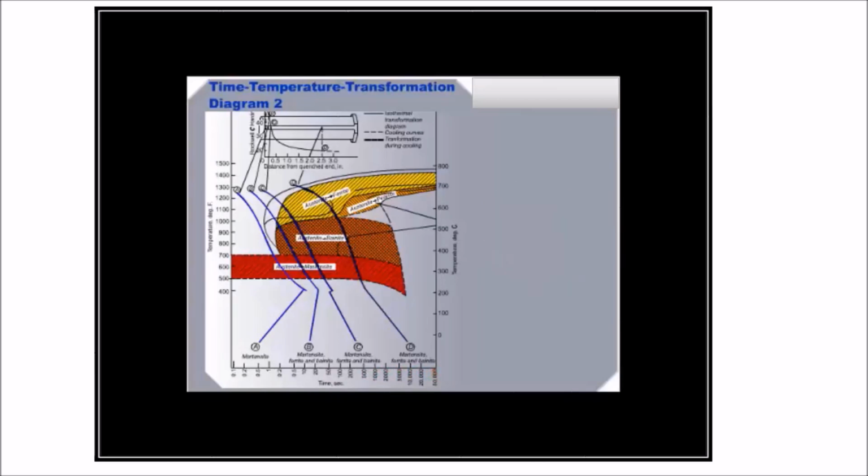As an example, curve A only passes through the austenite to martensite region, so the resulting microstructure is 100% martensite. The slower cooling rate, characterized by curve D, shows that the resulting microstructural components will be primarily ferrite, with only minor amounts of bainite and martensite. Since martensite can only transform from austenite, any austenite which transforms to ferrite or bainite cannot transform to martensite.